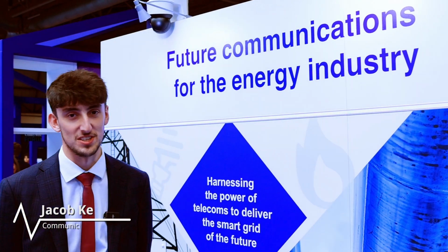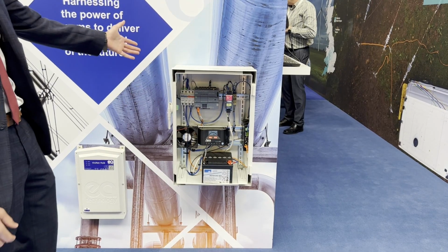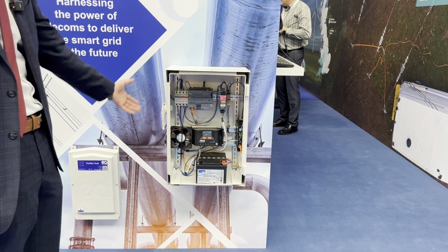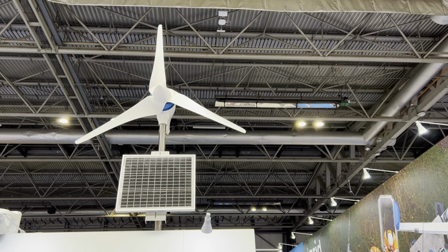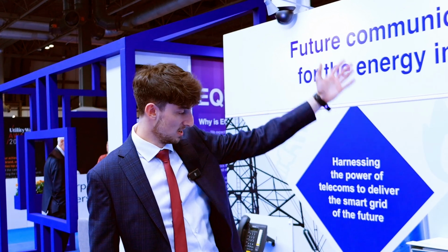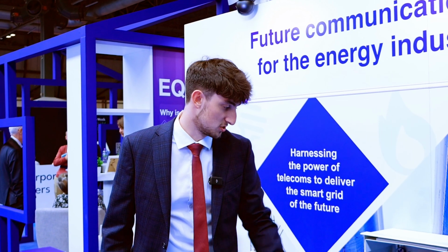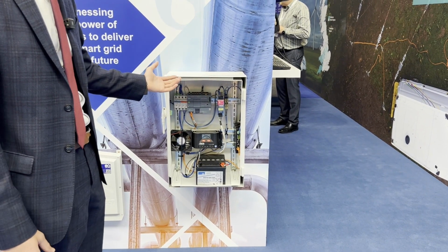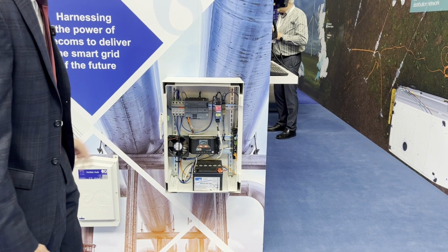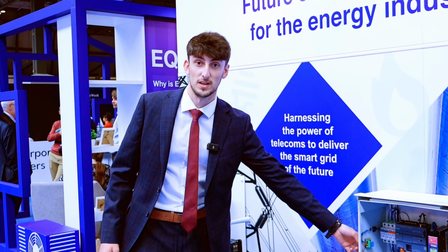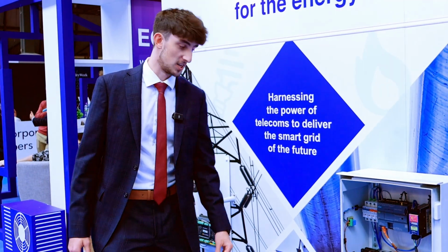Hiya, this is showcasing the capabilities of a private LTE network for utilities in general, so that would be electricity, gas and water. Here on our stand we've got potentially a rural device, so it could be for a water board where they don't have power to the devices, so they might have solar energy or wind energy powering a battery to keep up an LTE CPE, and also an RTU to perform functions such as turning a pump on or off or opening or closing a valve. And this would be just using a little antenna like this to connect back to an LTE base station.